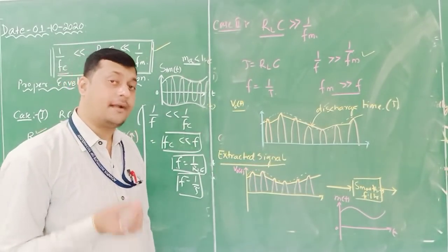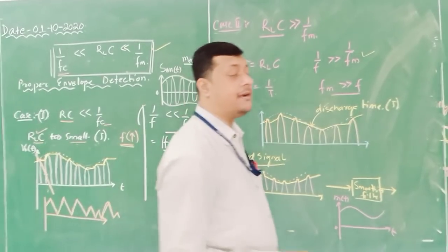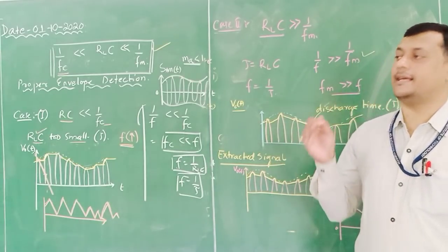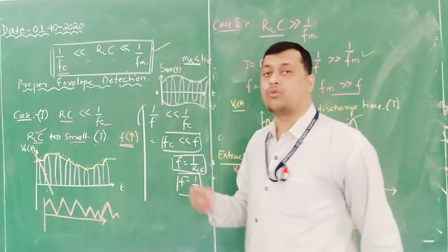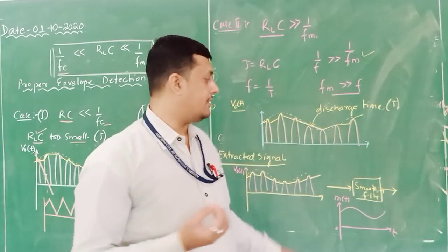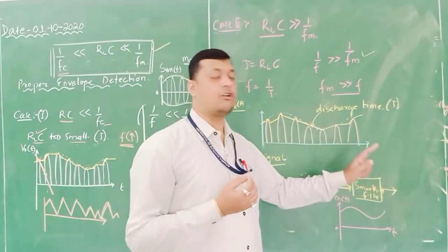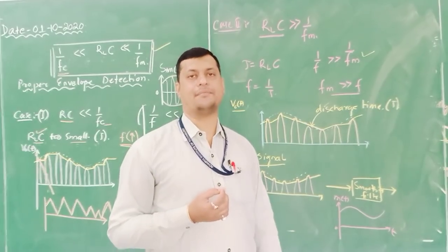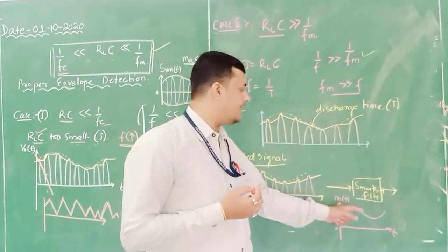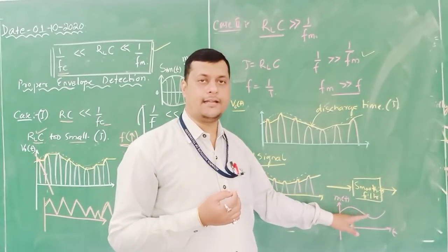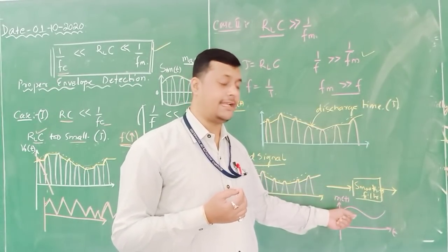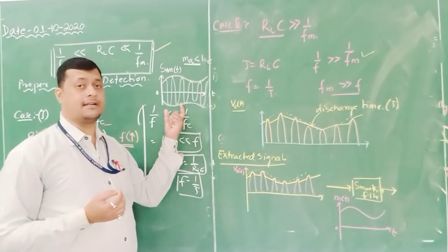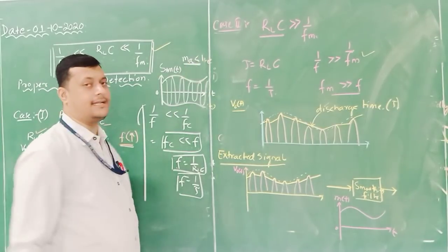Now what is the advantage of envelope detection? The envelope detection advantage is it also indirectly identifies the mode of operation. Now here you can see that my modulating signal is a cosine signal which starts with some DC offset value, and it indicates that if I modulate this modulating signal with a carrier, the modulated signal we generate will have MA less than 1.